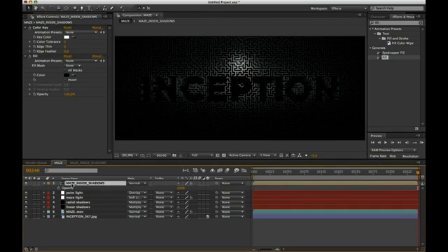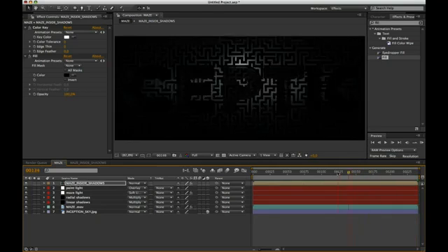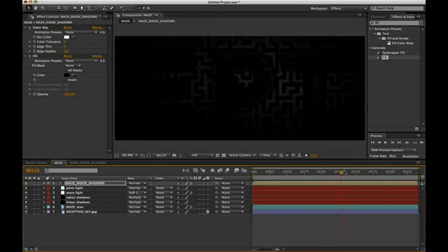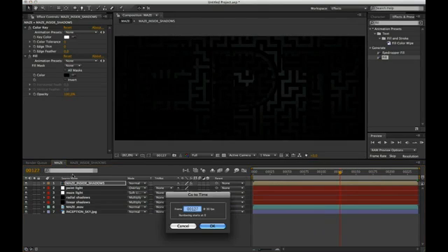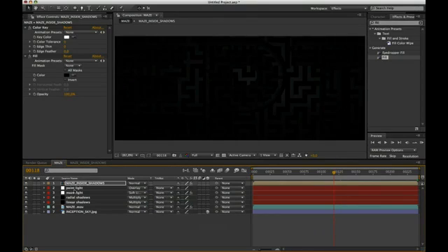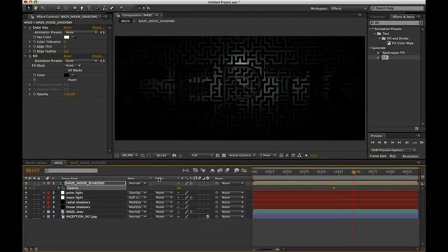We set the opacity to 60. OK. Here we go. This must also be animated. Go to 118 frame, and activate an opacity keyframe. Value is 0. Go to 147 frame, and restore the value to 60.